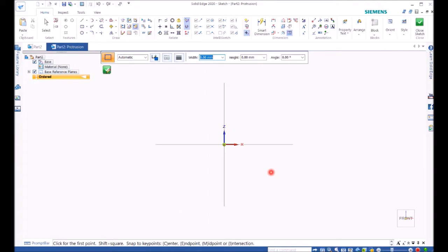But in terms of the model itself, without considering assembly, it would be the same. When you're considering the assembly, you always like to start from the middle. Since this is the exercise, I just do that randomly at any place. You click. After you click, you must release your mouse and drag. If you hold your mouse button down, you cannot control the dimension. Okay, you have to release your mouse and drag.